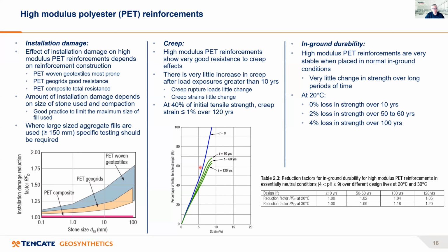Now, there are two ways of looking at this chart. You can look at it in terms of load only. So in this way, we look at it coming down this way and horizontal. So we may start off at time t equals 0, 100%. Then at 10 years, the tensile strength of the material left is somewhere just under 70%. But you can see all the change has occurred really in the first 10 years.